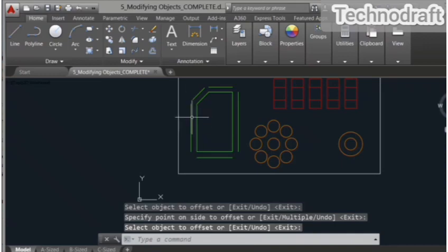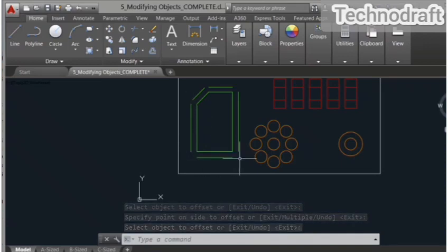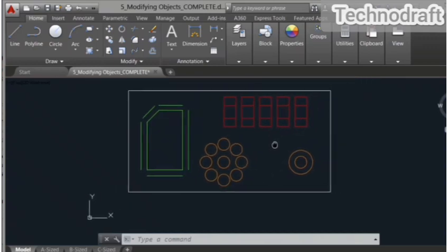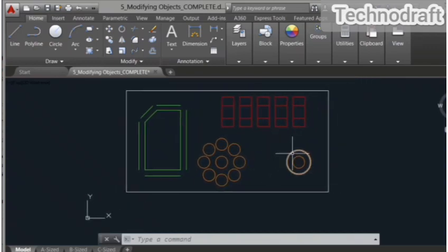So what I have got now is a group of lines waiting to be joined together, and we will look at that in a little while when we start using fillet and chamfer in the next video. I need to do the mirror command next, so I'm going to pan across a little bit and mirror these two circles here to the left to create another control button.